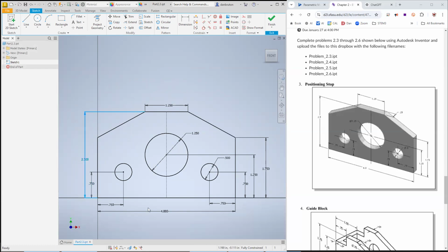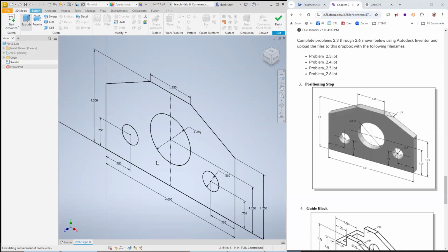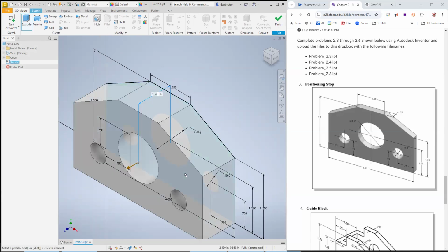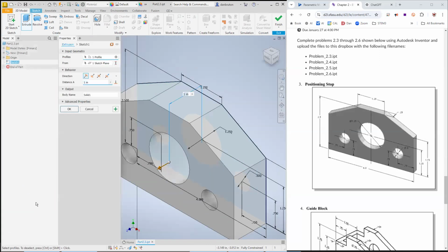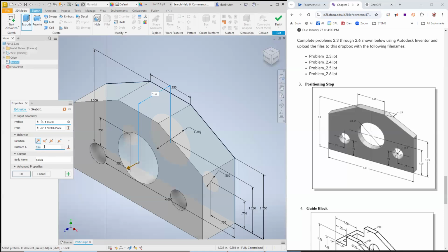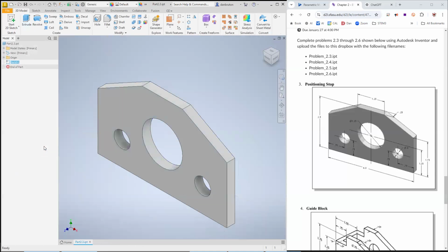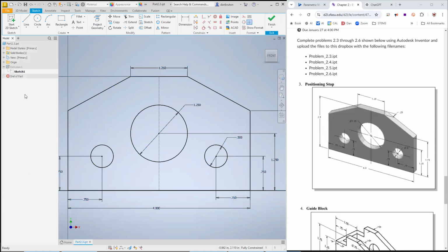But what I'm going to do now is extrude it the other way so that these dimensions are going to be on the front of the drawing. So that's what I was trying to get to before it crashed last time. So instead of extruding out this way by a distance of, oh, that kind of locked in there. I didn't really want that. 0.25 like that. And I hit enter too soon. So let's right click and say edit. And instead of, oh, I was editing the sketch, excuse me. So let me hit finish like there.